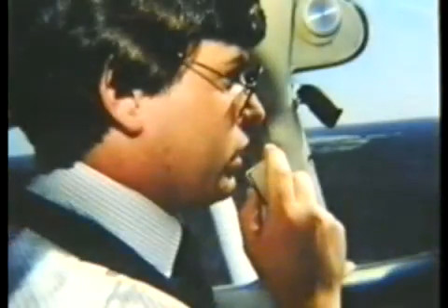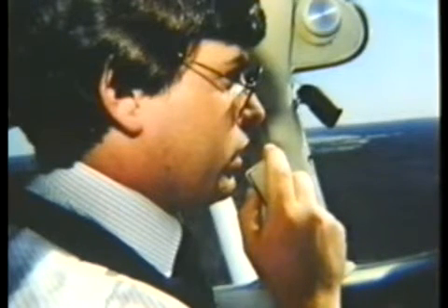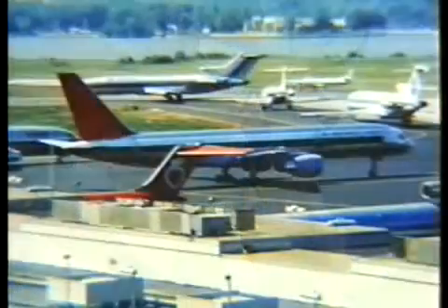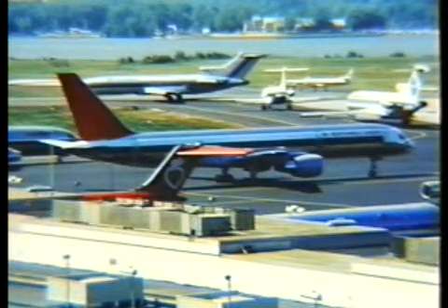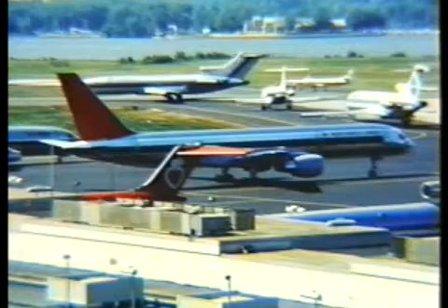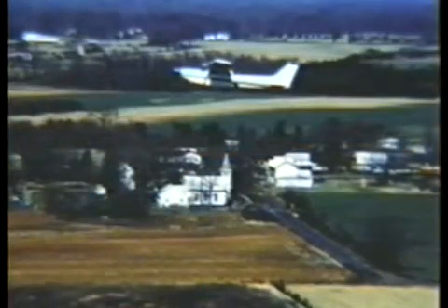Now communicate. Remember, control first, then communicate. There is no exception to this rule. However, if you're at an airport with a busy control tower, it's prudent to tell the tower what you're up to as soon as possible, but never at the risk of compromising your safety. When you're back at pattern altitude, power can be reduced and you can set up your next approach. Take your time, though, and make sure you pay particular attention to your checklist.